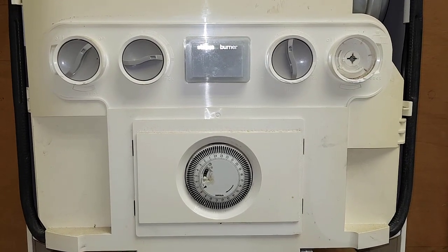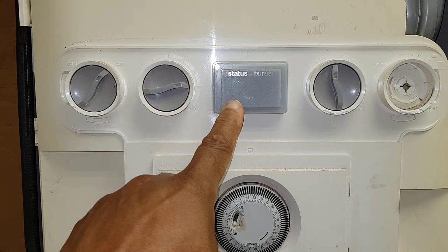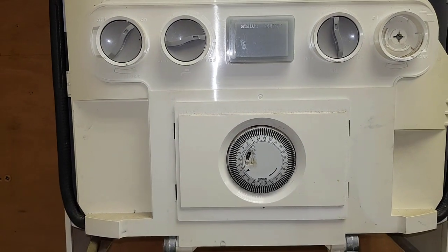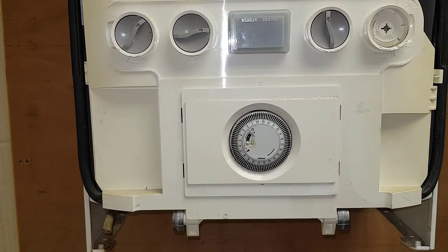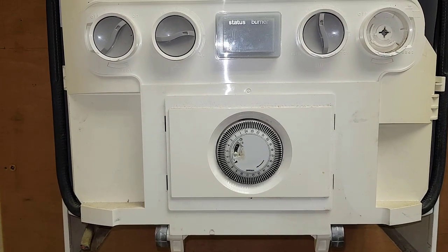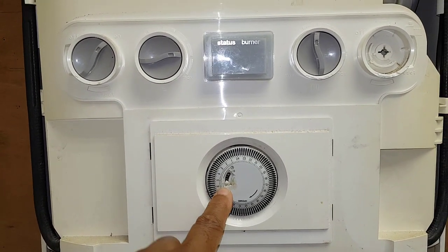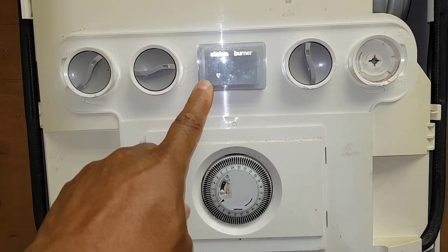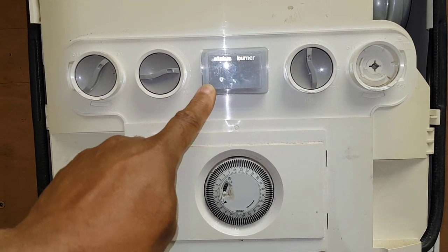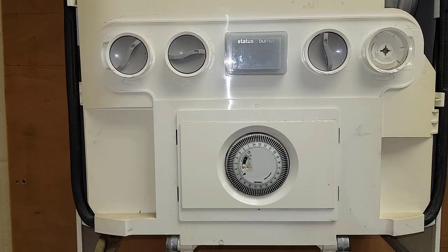Now, what if we don't get the C coming up on here, so that C doesn't come on? What would that mean? Do you know the answer to that? That means the thermostat isn't working. Right, okay. So the C's not come on, so we look at the thermostat. Let's look at how we could test the thermostat. If you bring the thermostat back in.